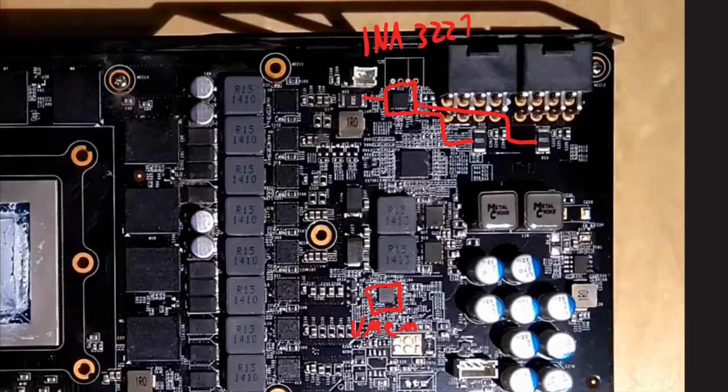Basically, your 12 volts power goes through this shunt, and because this is a 5 milliohm shunt, you will lose some power. Like if you have 12 volts here, you have like 11.995 volts here or something like that. And this voltage drop changes by how much current you are pulling.